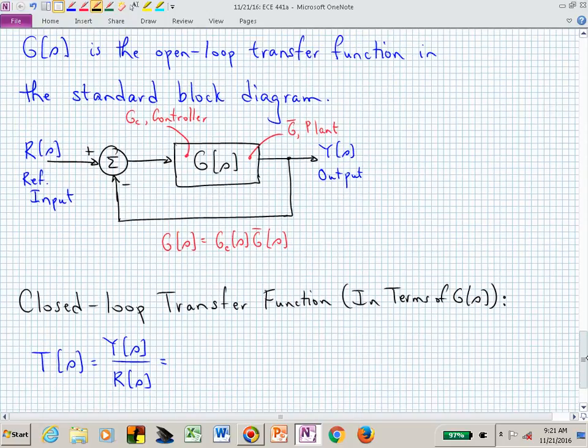Now, what's the closed loop transfer function if our open loop transfer function we'll just call G? In this particular block diagram, what is the expression for T? I guess we needed some zero factors to get us up instead of just continually having pole factors that put us down. But if we had zero factors in there, the slopes would be positive, or going up, by the same amount, just in the opposite direction. What is T of s?